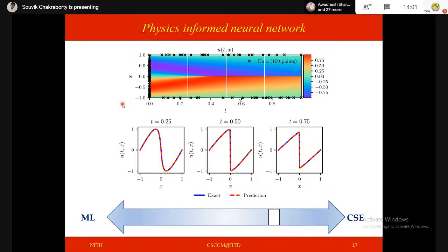You will realize that this is not a simple problem because at t equal to 0.5, around here, you see there is a sharp change in the gradient. And so, if you don't place many mesh points or many elements here, your finite element will not be able to track this sharp change in the gradient. So you need a very fine mesh at x equal to 0, and only then will you be able to track this change. So this is not a trivial problem to solve.